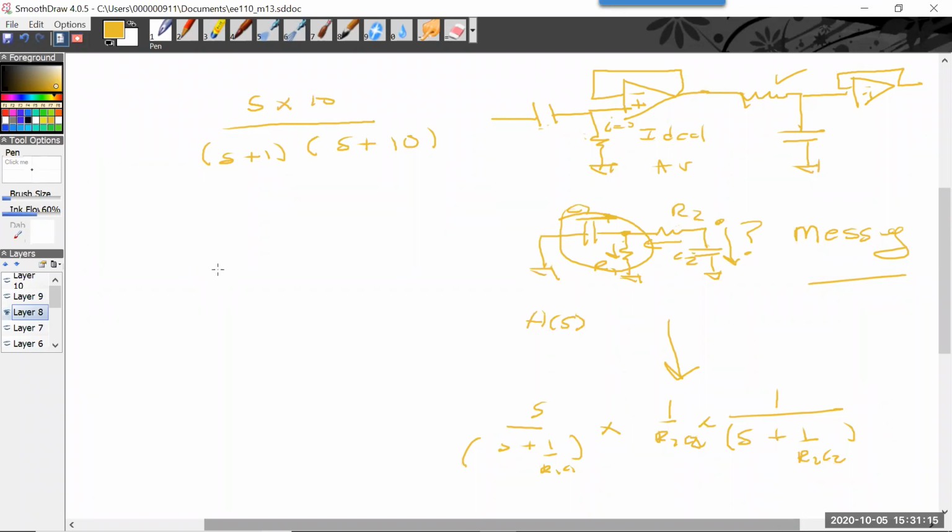And this is something that you might forget, but the impedance of an ideal voltage source equals 0. So an ideal voltage source won't affect the circuit. Now, of course, after doing the lab, you know that they tend to have 50 ohms. So if I have 100 ohms here, and then there's a 100 ohm series resistance, it changes the time constant of the circuit. But as long as we keep this resistance much, much greater than 50 ohms, it behaves like an ideal circuit.